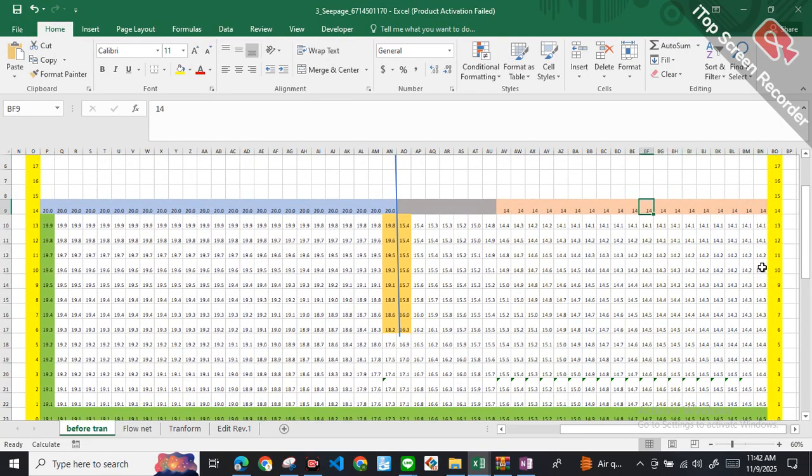After that we are going to focus on this cell. This cell is going to be a bit different. As explained before, for this cell value we are going to depend on this cell and the below cell, but on the right we cannot focus on this cell because we have a seed pile in between. It divides our boundary. So for this cell we need to bounce back onto this cell value. So for this cell we are just taking the average of this cell, this cell, this cell, and again it bounces back to 19.8 value. So you might be a bit confused, like, where is this 19.8 value coming from?